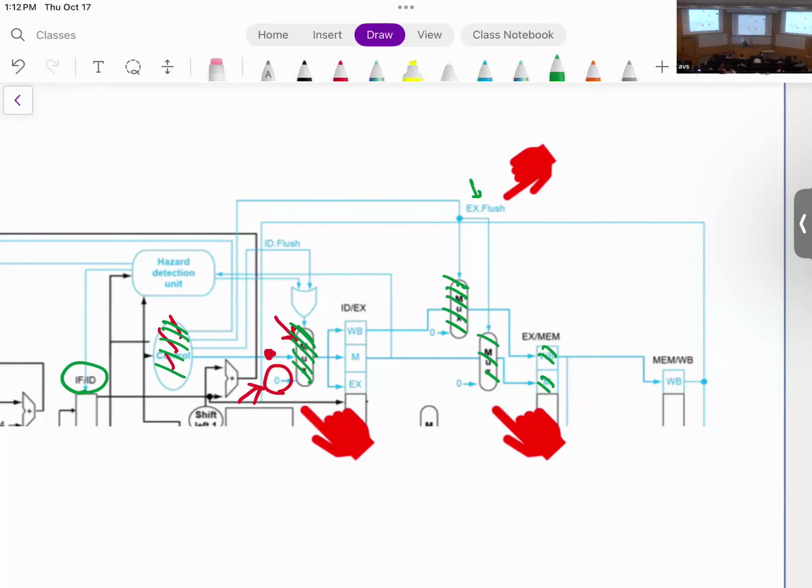So the question is, what if you already write to a register? Again, the timing thankfully prevents that from happening. Remember that we know in the memory stage whether or not the branch is taken, and by that time, the previous instruction hasn't reached the write back stage yet. So they're always guarded by the branch. The branch is in the mem stage, every other instruction is previous. Now the next instruction goes to the memory stage, and now you can flush it out.